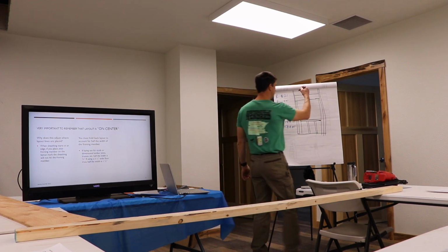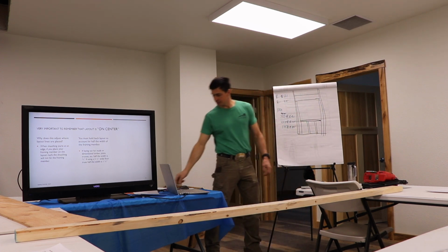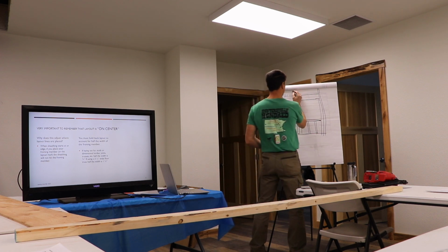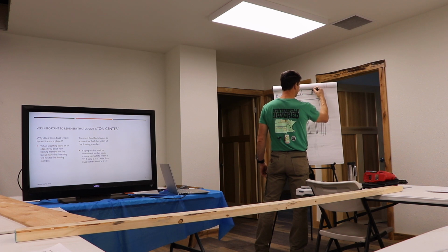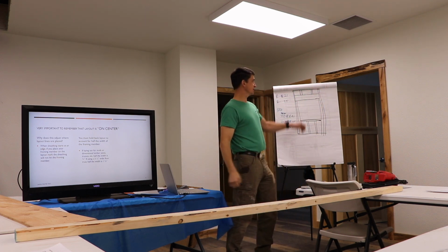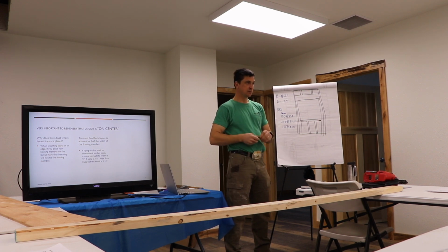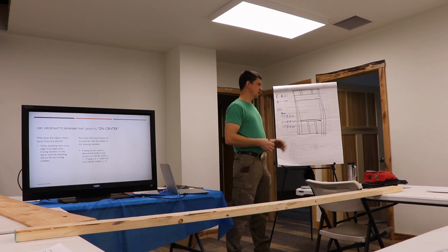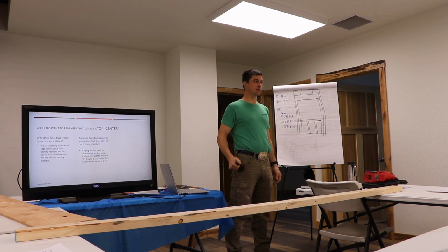So they also, with the markers, so it's easier to see. So here's your top plate, and then most of the time, the header's not going to be all the way to the top of the wall. And so then they call these little guys cripples. And you will run into a lot of terms in the trades that get mixed and matched and thrown around a bunch.